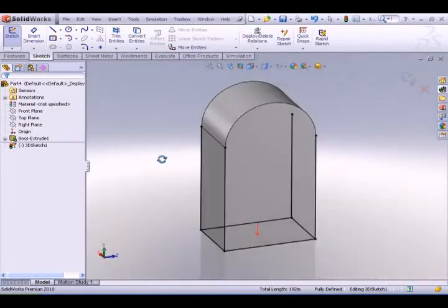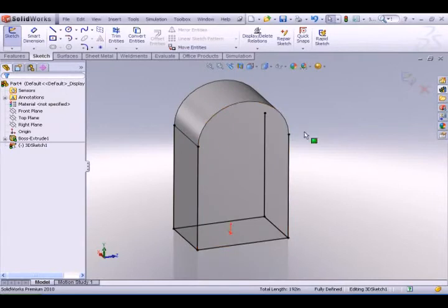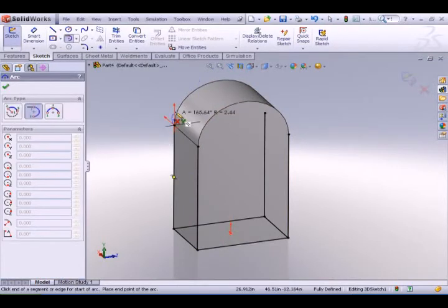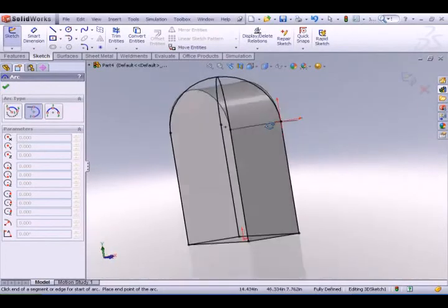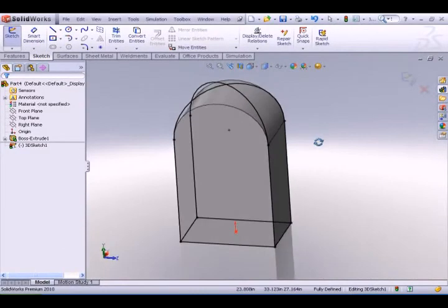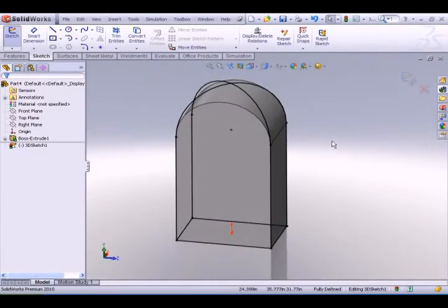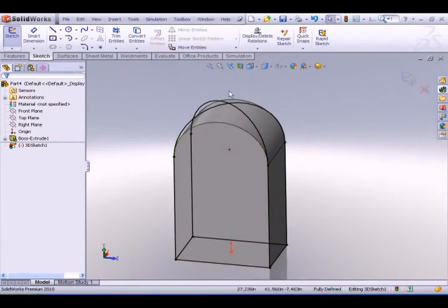And now you'll notice this is the majority of the 3D sketch that I was trying to create. The only thing is I've got this body kind of floating in the middle, getting in my way. I'll show you how to deal with that in a second. I'll grab my tangent arc. Make sure to go up and leave from the direction you want to leave from. Notice it's very easy to just grab these tangent arcs, throw them in here, and everything looks very good. See how quickly that worked? I can come back in on the front plane and add another sketch if I need to. I can use any method I want to go ahead and use that cross member.